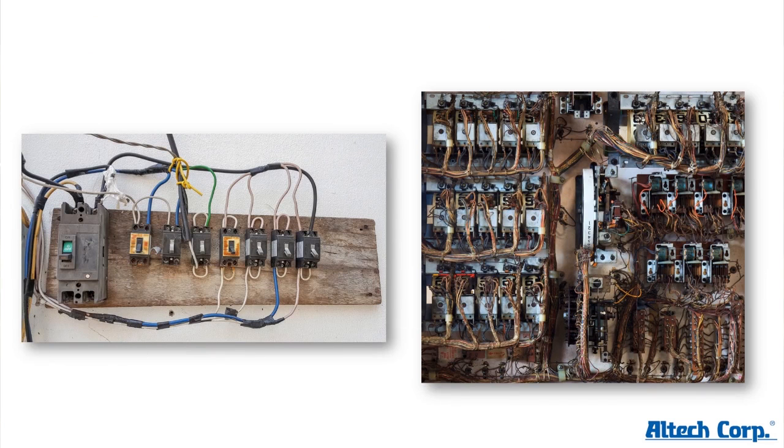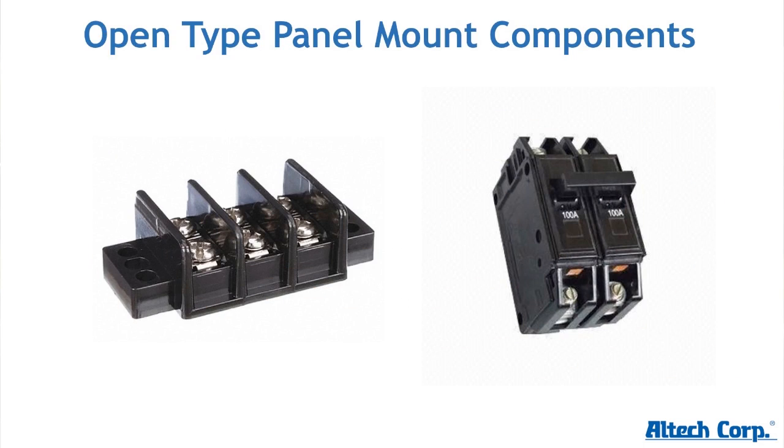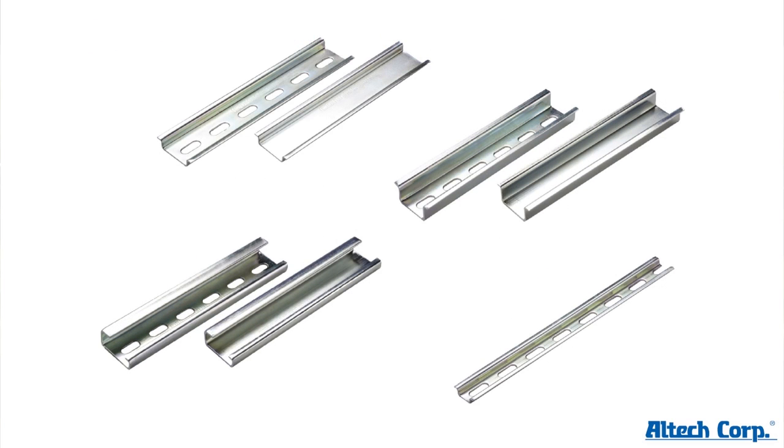Any non-licensed electrician or any maintenance person opening a panel could get electrocuted very easily, not even thinking about the fact that all these connection points are live. So with the DIN rail then also came a lot of touch-proof components.